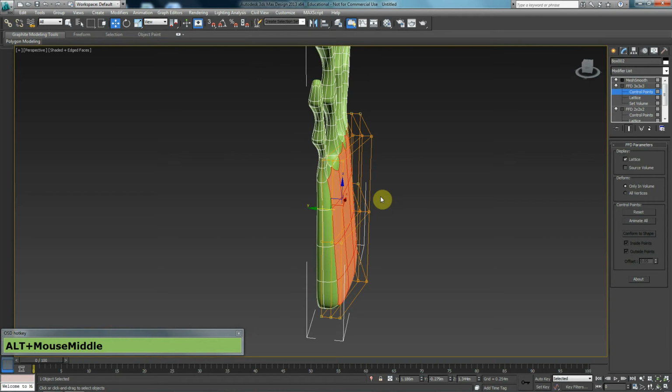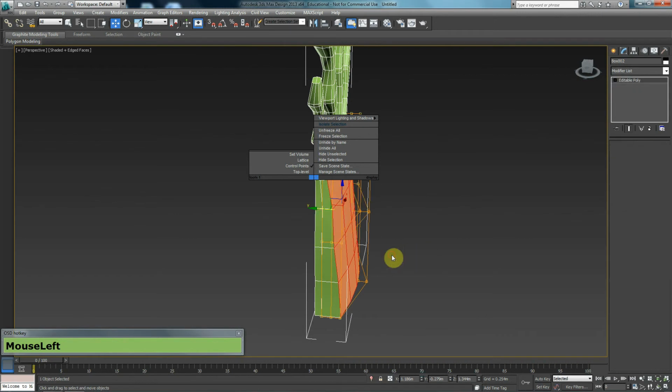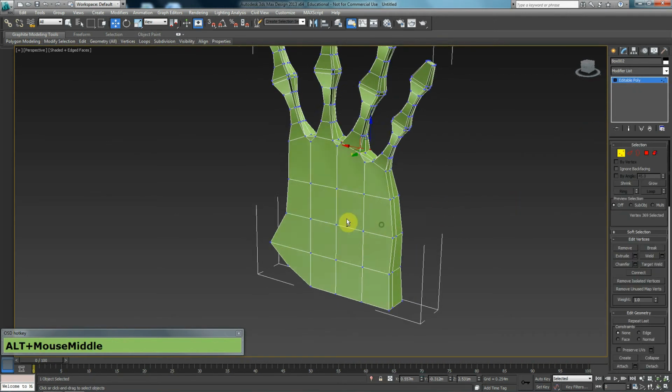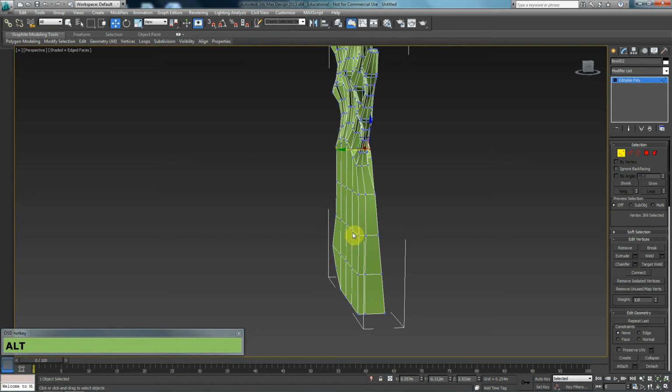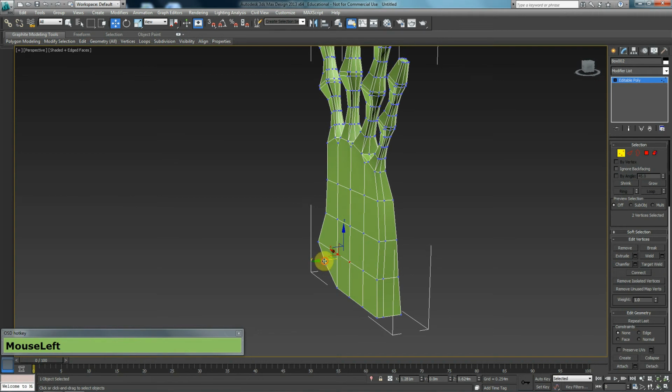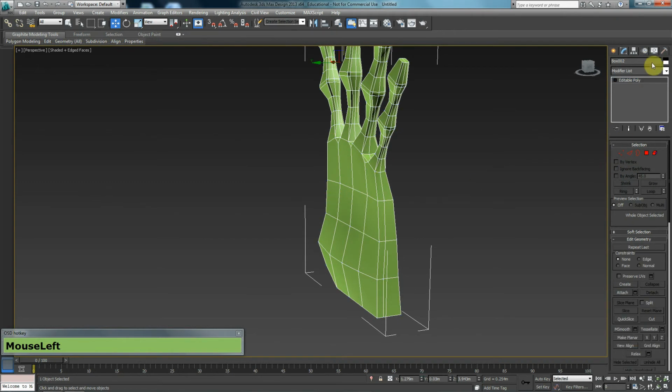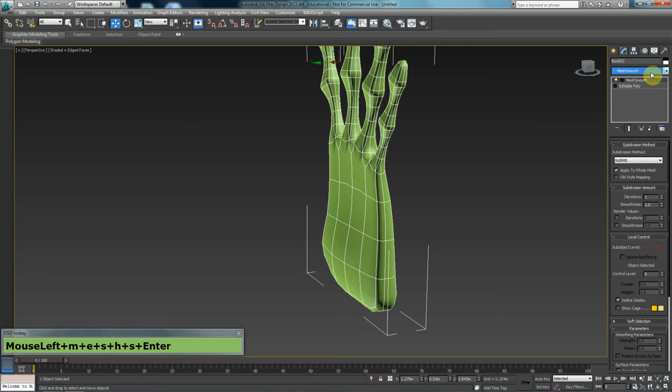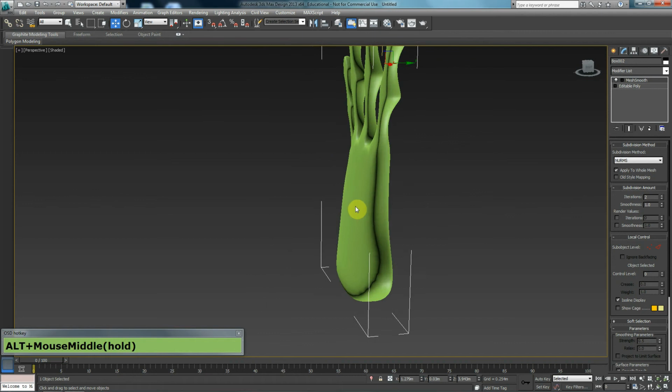And what I may also want to do is turn mesh smooth off and convert it to editable poly so we have a fresh editable poly. You don't want to collapse down the mesh smooth, that's very important. So if this is the front bit, I might want to play around with this, push a few of these vertices out a tiny bit, push a couple in maybe. And if we put a mesh smooth on top, it roughly looks slightly better.